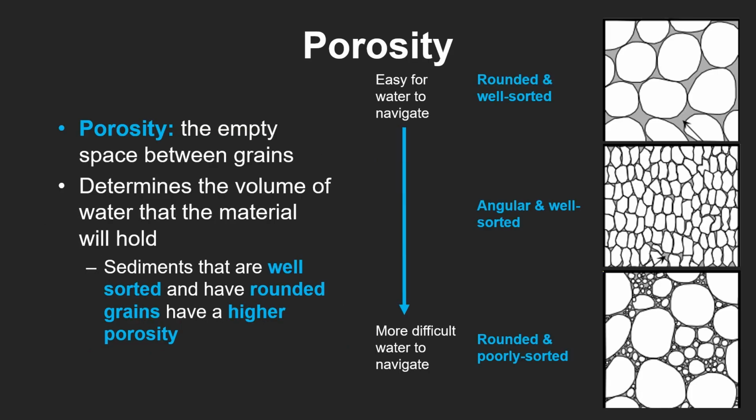Porosity describes how much open space a material has to store water, and grain size can influence this, though grain shape often matters even more. Permeability describes how easily water can flow through those spaces, which depends on how well the pores are connected. Together, these properties determine how quickly groundwater travels and how much water an aquifer can hold.